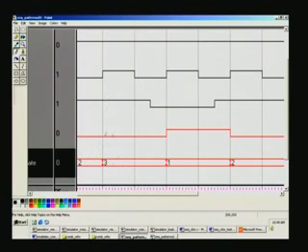So its corresponding output will get reflected only here, because it has to wait for entering the state only at the next positive edge. It has just entered the state, right? That state will be processed only at the next clock edge. Only after you process that particular state, you can get the output. That's why it's happening. Are we clear with this?